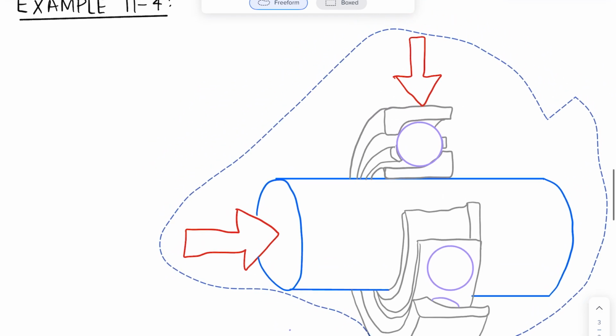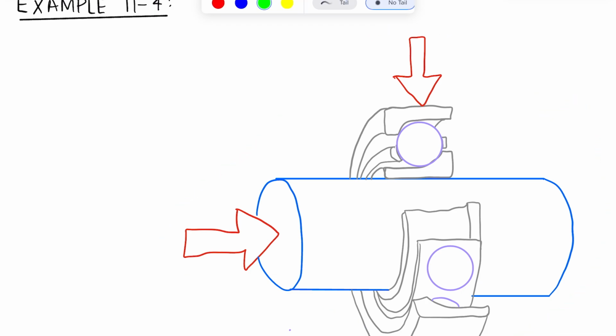So when this question says we have an angular contact ball bearing, what that refers to is this shape of the inner and outer raceways that allows for this ball-shaped bearing to absorb both radial loads and axial thrust loads.